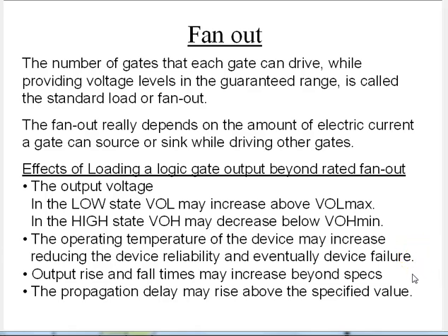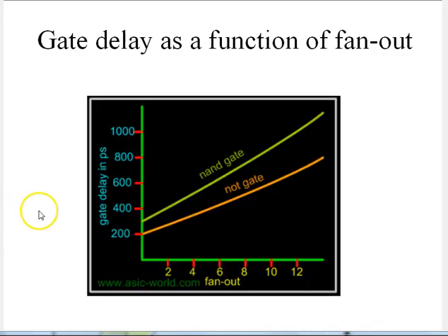But you could experience output rise and fall times increasing beyond spec, and the propagation delay increasing. Again, that propagation delay increasing is going to affect how fast you can run your circuit, or the frequency at which you can run your circuit.